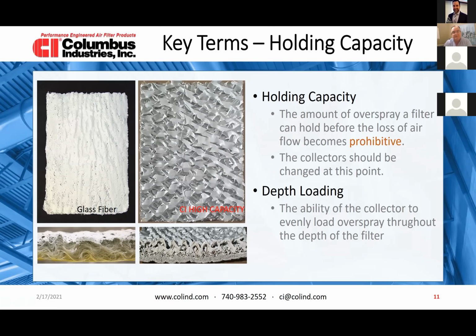Of paint collectors, we have ample surface area that is open, and as you can see from this side view, it is loading the paint not just on the surface, not only on the front mesh, but it's also loading throughout the whole matrix, all the way down to the synthetic that's there. The specific filter does require the synthetic because of the nature of the particle, the size of the particle. And that's why we have what we call depth loading versus face loading.